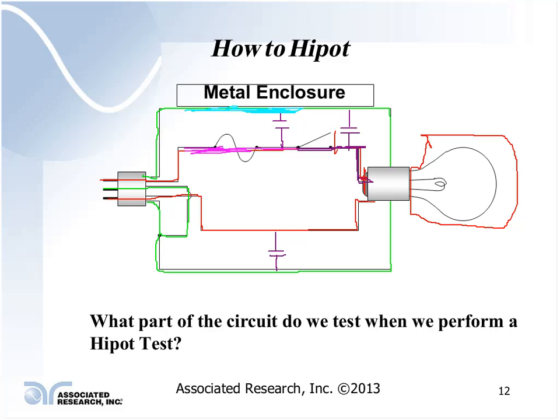But I have seen in a lot of cases where, if I have my limit set tight enough, I can tell whether I have my power switch in the open or closed position by setting up both a high and a low limit. At a minimum, I know whether I have an open test lead or not.